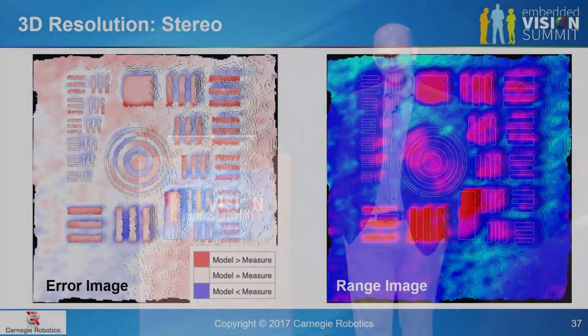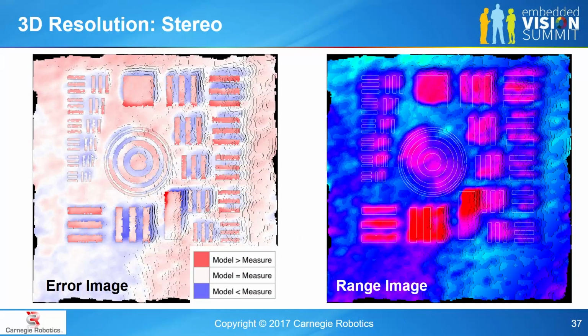Yeah. So in your test result of the stereo camera, you said the bleeding between the vertical bars is caused by the optimization from the neighborhood, right? Mm-hmm. But if you do the optimization from multiple directions of scanline, will it improve? That would help. This camera uses a 4-direction optimization. It's not an 8-direction system because that would increase the latency of the camera. I see. So that's part of what's causing this. Yeah. But it's also just the ambiguity on vertical edges versus horizontal edges because of the two different viewpoints. Okay, thank you.